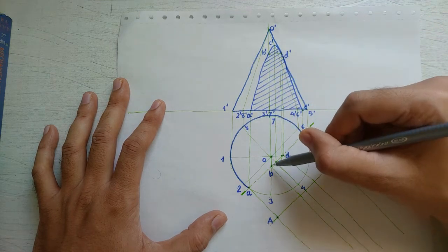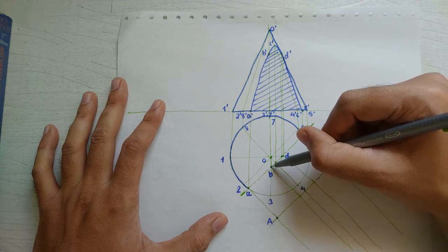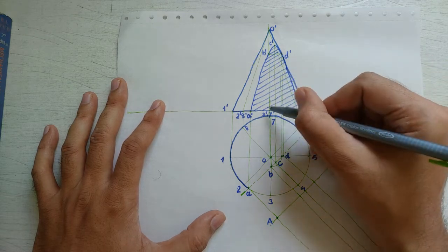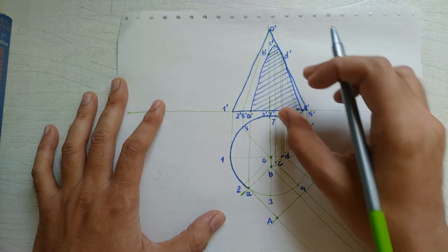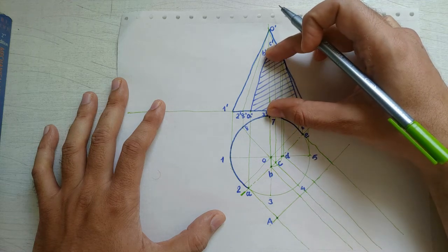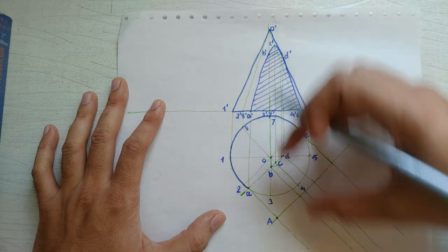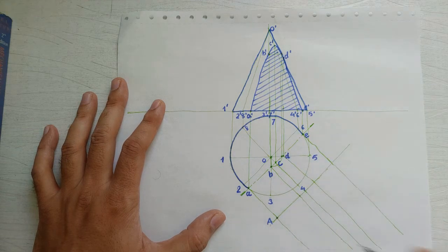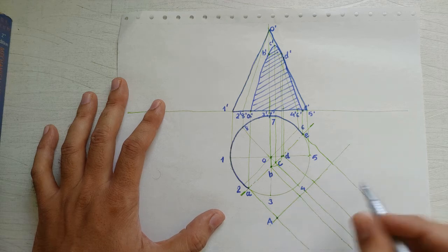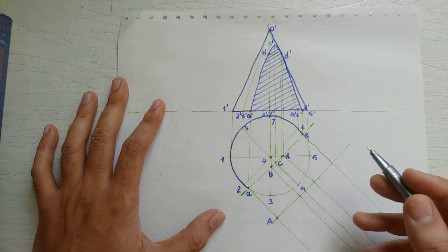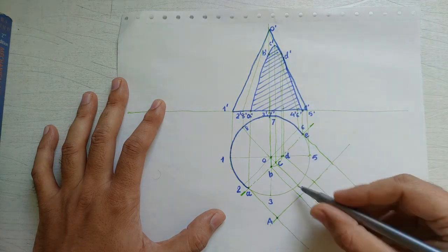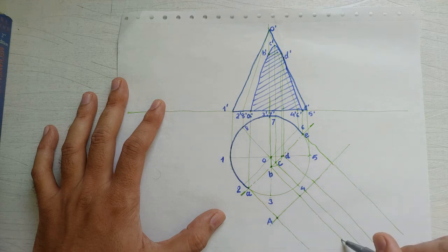I am repeating, I will look at this projection line which is coming from B, and on this line I will measure the distance from XY to B prime using compass. So basically I am measuring this distance, and that distance I will put over here. So from this point to the distance, so that means I am taking an arc. I am taking this distance in the compass, then I will take this point as center and I will make arc on this line. So that gives me point B.